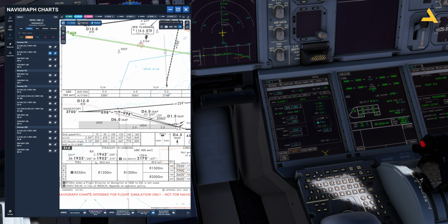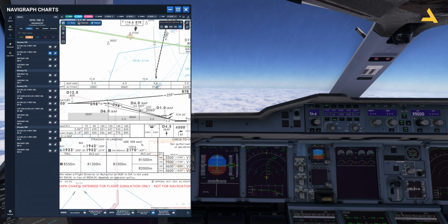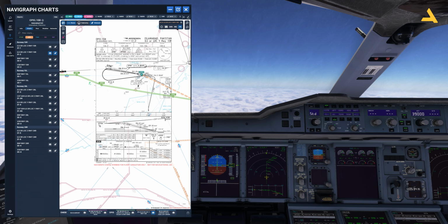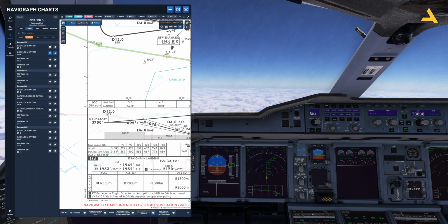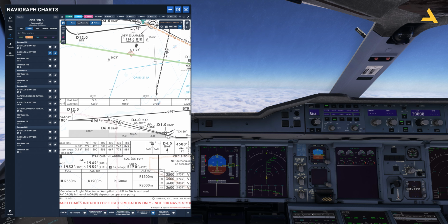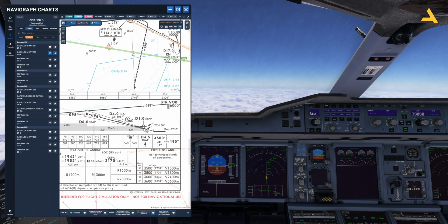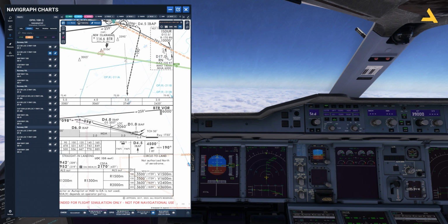There is actually a reference chart in which you can see what should be the speed for the minimums. You can just search over the internet. So it is the altitude at which you make sure that the plane is aligned with the runway, and you can see the runway for the landing. The target altitude for the descent will be 3,700. This is the point at which I should be, just 12 nautical miles before the runway. And then I will proceed towards the landing. The runway elevation is 1,733 feet above the sea level.